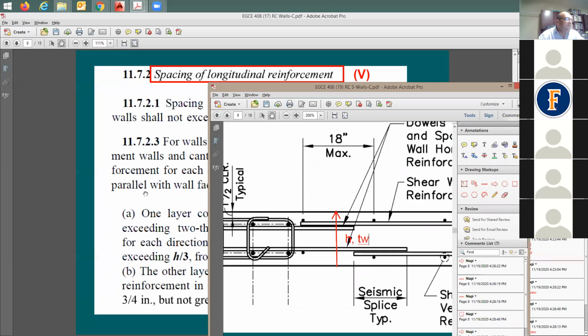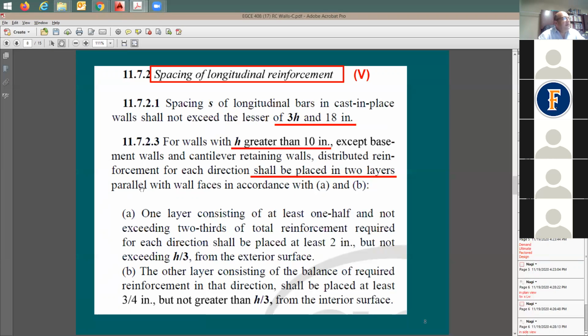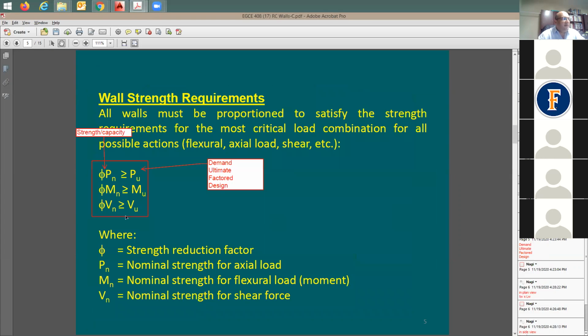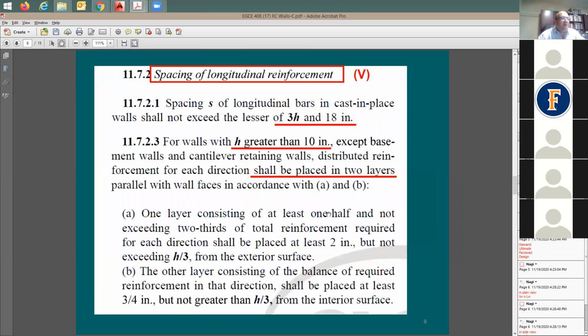So, okay. So the spacing here, you cannot just have the same reinforcing bars and satisfy the requirements of this section, and you satisfy the requirements of the trench, and then you put the bar spacing, let's say, to be at 4 feet on center. Now you're going to see lots of cracks in the wall. This is not good. So you'd like to have it closed. So to have it closed spacing, I'm going to go here to a maximum of 18 inch. So you cannot go beyond 18 inch. So in any wall, you cannot go beyond 18 inch.